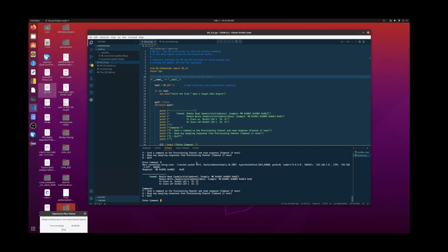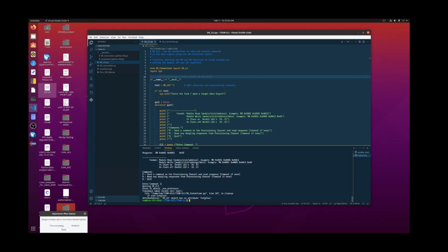You can explore the module identifier and interface identifiers in an interface map table in the C code. And when we come to other systems that don't use the data engine adapter and that use the actual data engine and may have more receive modules, this table will change so that the interface and module numbers will probably change, but they'll be defined in that particular table. We can now quit the interface and go back. So that's a brief walkthrough of bringing up the interface on the particular module.